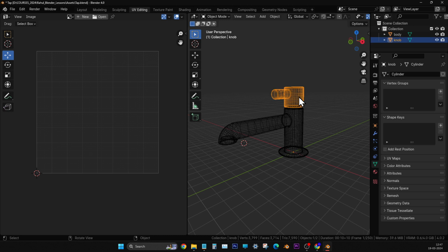For every object he does not need to select and then apply a texture. Whatever texture we have painted, we will give them that texture and the mesh file also. So he will have to apply it again in his software, Unity or Unreal. While doing that, he will feel that for every object I have to apply a different shader, that is material, and then again apply the same texture, and for another object again apply a different material and apply the same texture. If it is the same texture, we can have only one material and one texture, like that he will do.